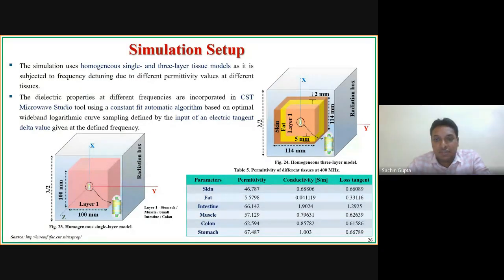Okay. Yeah. Here the frequency band considered was a lower frequency band only, which means we have targeted MICS, WMTS, and ISM. So hardly it is going up to 3 gigahertz. So the input power would be very small, in milliwatts if you calculate the overall power, because this capsule will be powered by a small battery.